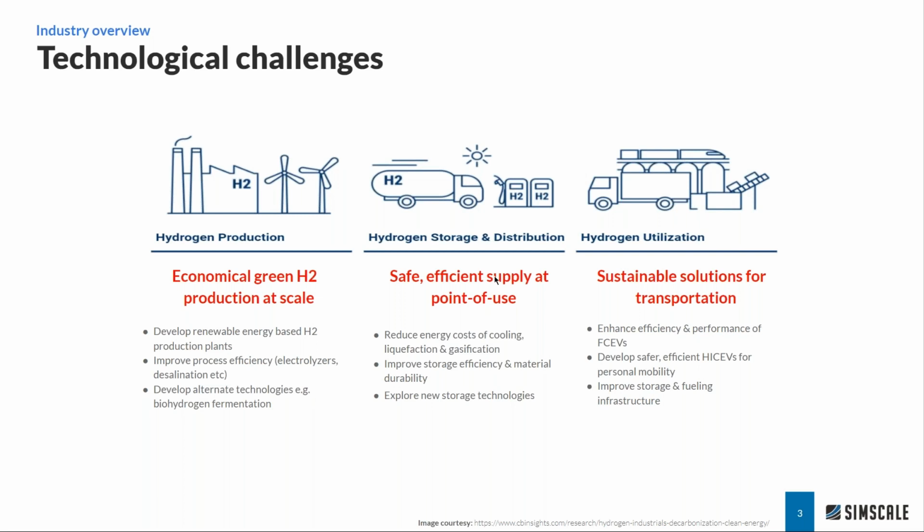And next in the story is how hydrogen can be more efficiently stored and distributed. It's a difficult element to handle in terms of its density, in terms of its flammability. And an interesting tidbit here is that right now, a lot of hydrogen transport happens using truck systems as liquefied hydrogen. And 30% of the energy in liquid hydrogen is actually lost either in the form of losses to the environment, or simply in the process of converting gas to liquid and then back to gas for utilization. I mean, what a waste, right? So there's definitely a lot of room for efficiency improvements here.